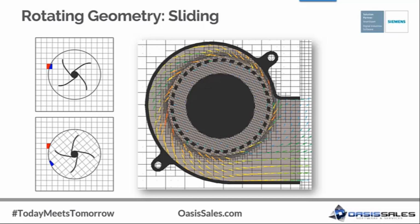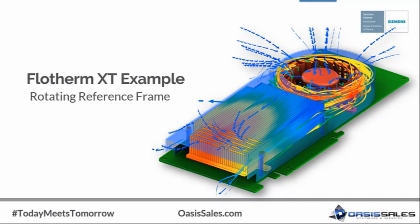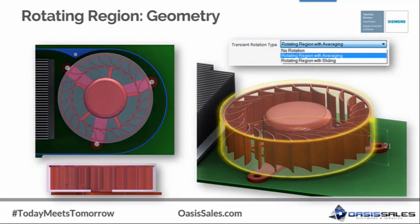We'll finish up with a quick example from FloTHERM XT of a graphics card using the rotating reference frame approach. The first step will be to create geometry that will become the rotating region. If you look at the image in the upper left, you'll notice that I've kept the boundary of the rotating region some distance away from the boundary of the graphics card cover, which will result in a more uniform flow condition at the boundary of the rotating region.